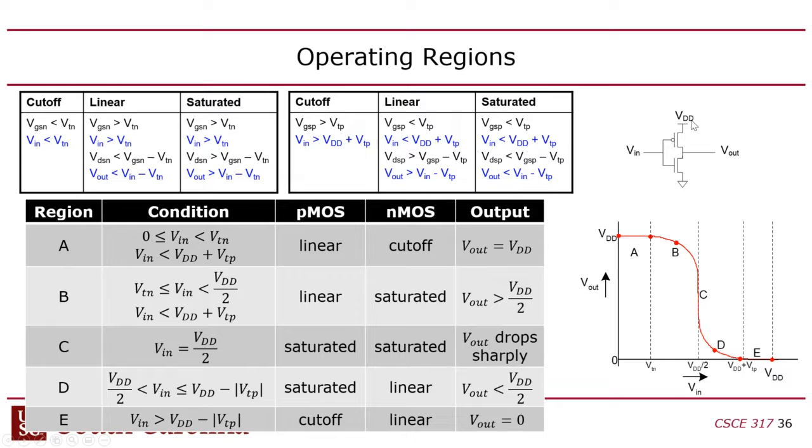And you might say, well, you just don't do that. Well, you have to do it at some point. Whenever the transistor switches, you're going to have to be in this state at least for some amount of time, right? You're going to be in saturation mode in both transistors. And this is where you lose power. This is why your cell phone battery is going to die after a day or so, because you switch this guy and there's a time when both transistors are in saturation mode. And it's unavoidable.